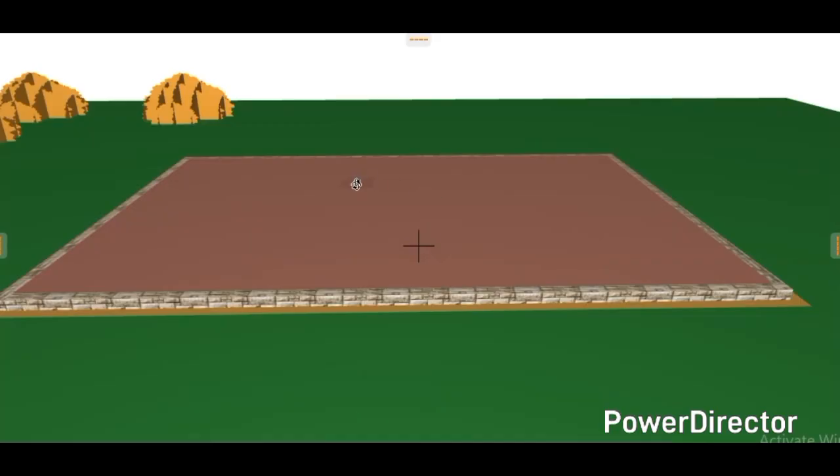So anti-termite is poured over all this place to keep off insects that might invade this building in the future. Likely they can cause a lot of destruction, especially on the wooden parts, doors, wooden doors and the rest. So anti-termite is being poured all the way now to keep them away. So it is treated as an item. There's no way I can demonstrate that now using an Archicad program. So just take it that anti-termite is being poured all over this place.